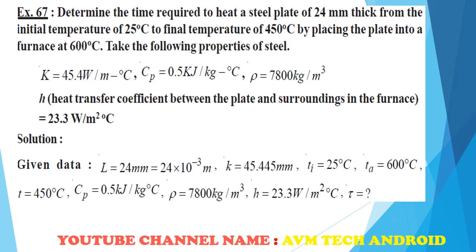Third, again you can see that is related to industry, where the data given is: determine the time required to heat a steel plate of 24 mm thickness from the initial temperature of 25 degrees Celsius to a final temperature of 450 degrees Celsius by placing the plate into the furnace at 600 degrees Celsius. Take the following properties of the steel.